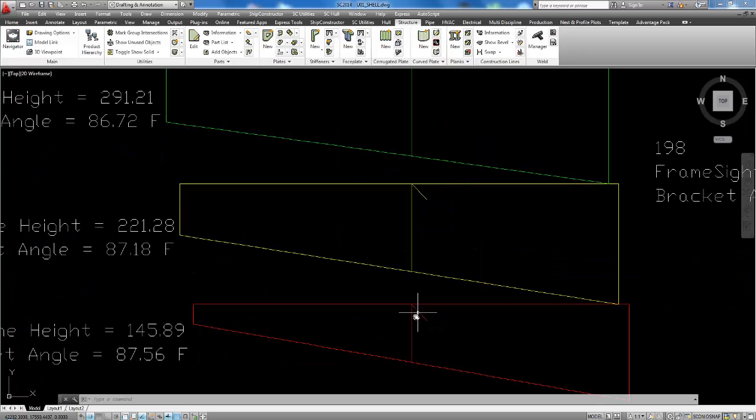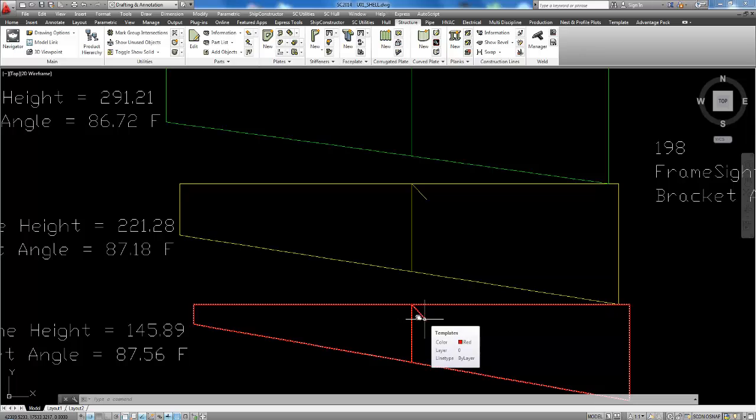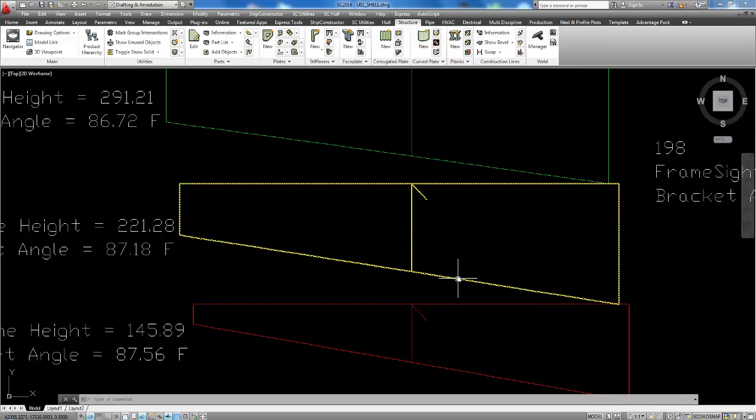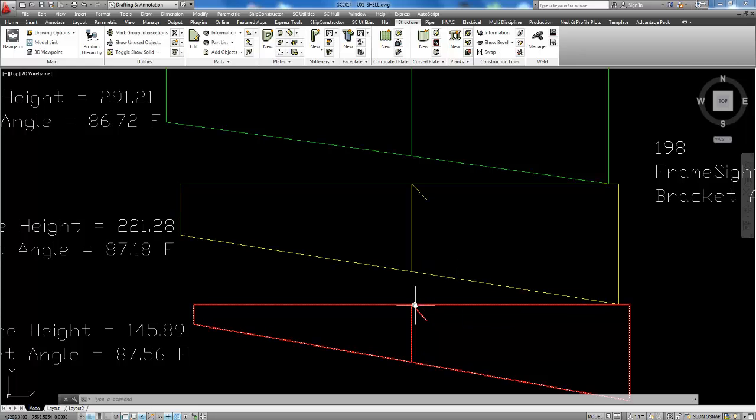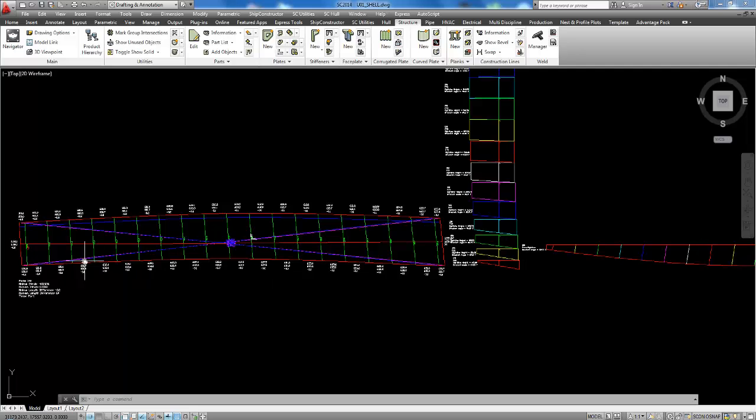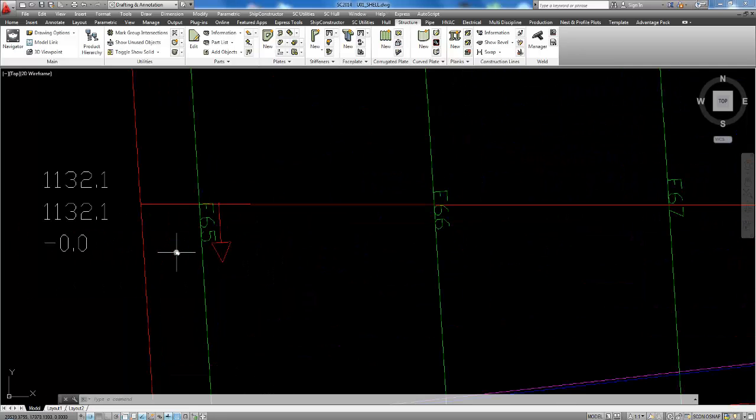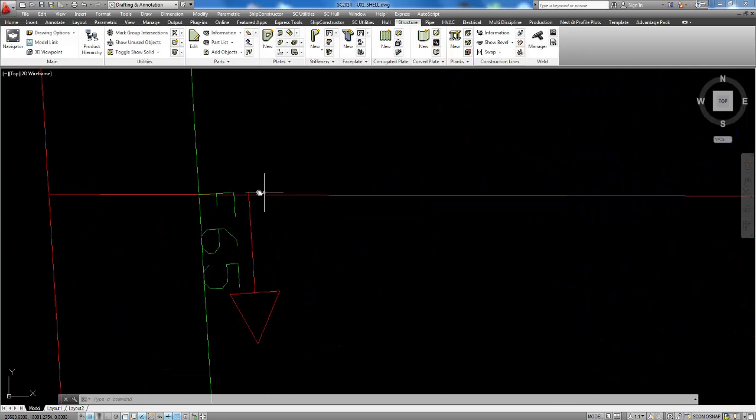On each transverse template, the mark line of the sight line has a symbol for correct positioning of this template on the plate for bending. The direction of this symbol corresponds to the alignment icon, this red arrow, which is placed on the plate as a mark line.